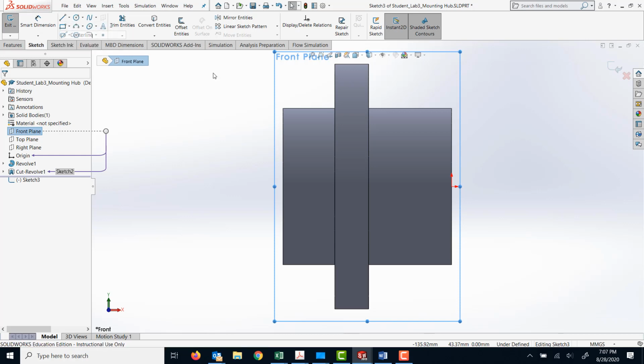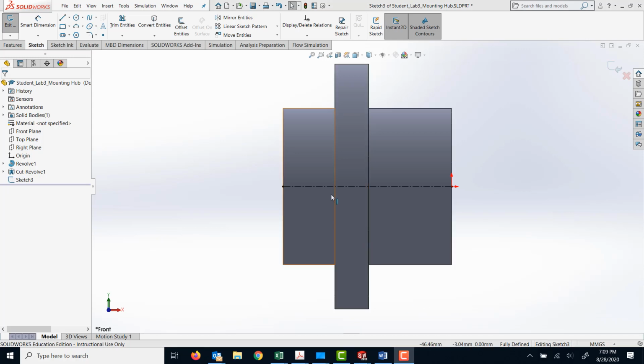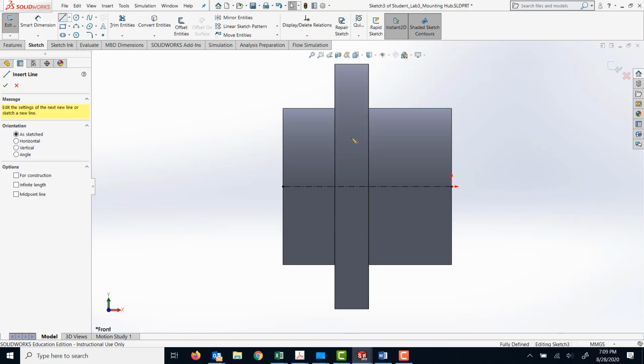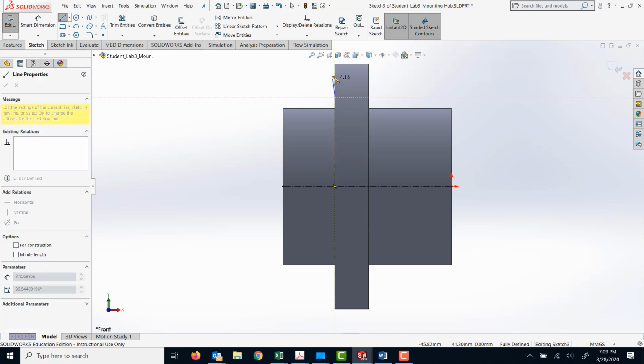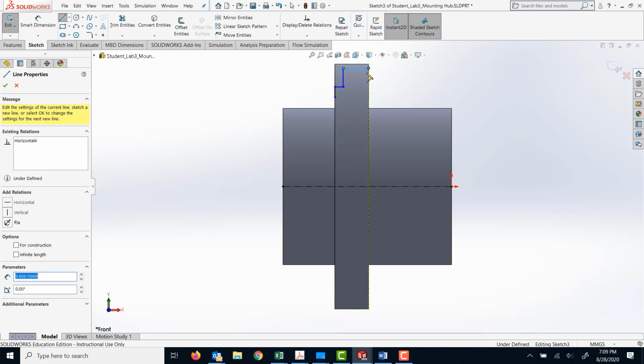The first thing I'm gonna do is create a center line, that I will simply use for the axis. So I'm gonna draw a line, and I'm gonna make it coincident somewhere there. I'm gonna go up somewhere there, move up, and then go up like that, come across, align with this edge, and come across, and then just close the sketch.